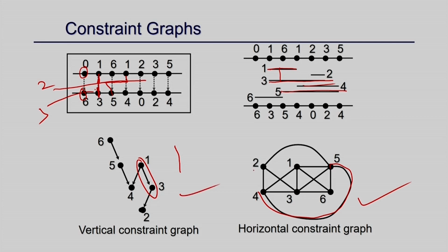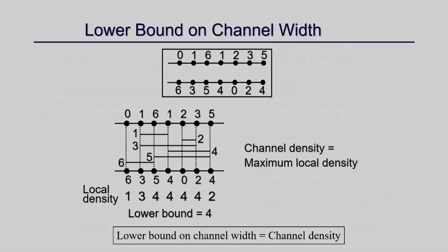So, you can extract those vertical constraints and horizontal constraints, and using that you can solve your problem, and you can identify the minimum number of tracks required using some logic also, which is the channel density. There are a lot of algorithms, like the left edge algorithm and other solving algorithms, which can handle dogleg connections or the VHV model and all. Again, I am not going into detail of those algorithms, but just to give you the problem flavor, what the channel routing problem is and what is happening here.